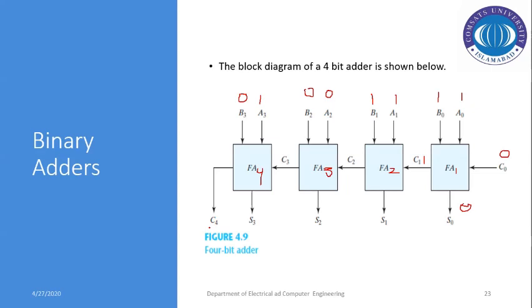We started our discussion by defining the combinational logic modules, and we said that these are just the interconnection of gates, and the important point was that these sorts of circuits don't possess any memory element or feedback element. Then we switched to the design principles, and we studied the 4 design steps which we opt for in order to implement the combinational logic modules. First is to define the inputs and outputs. The second step was to define the relationship between the inputs and outputs in terms of the truth table. The third is the simplification of the Boolean function if possible, and the fourth is implementation and verification.